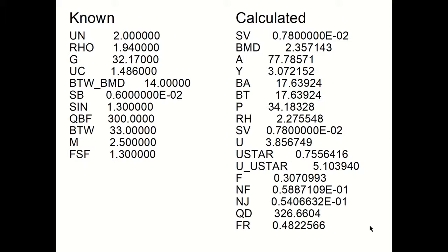Your first tendency, especially after taking a lot of structural engineering classes, would be to actually accept that larger value. In natural channel design, that may not always be a good decision, because that may be denying the flow which is above bankful from reaching out into the floodplains. And so putting in a larger size cross-section actually might entrench the channel more. So it's not always a good decision to simply be conservative.